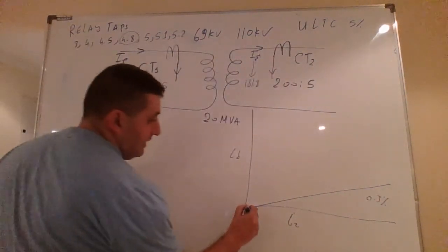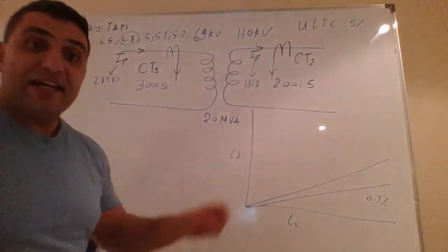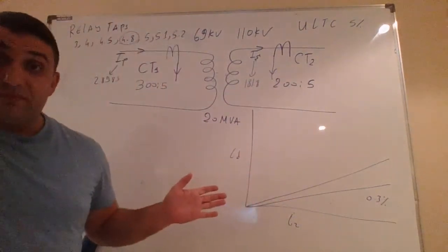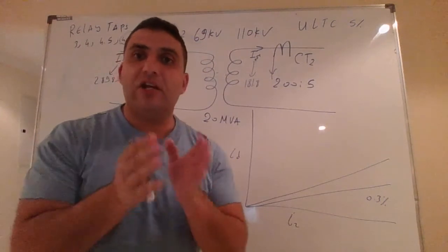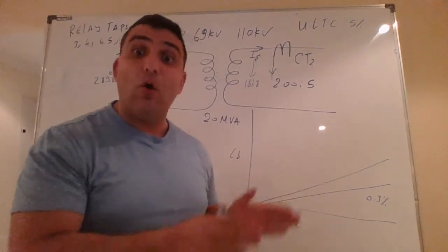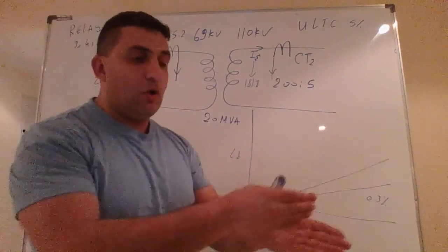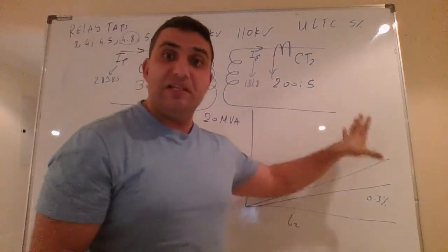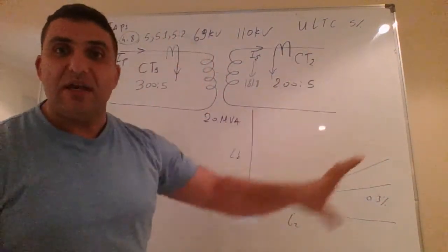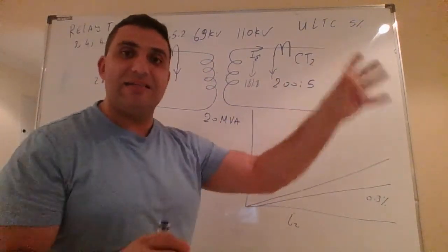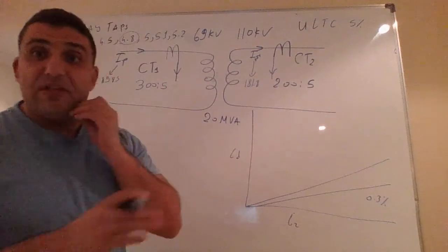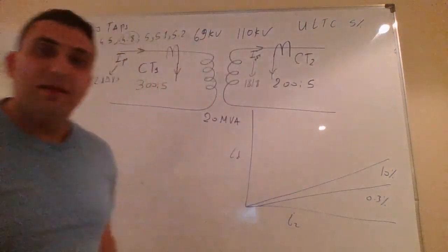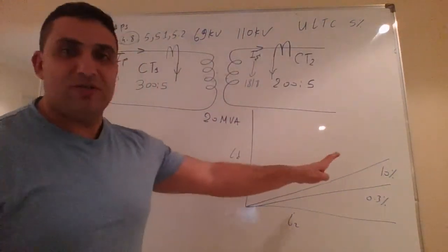The second error that we discussed was the CT error. Now, two options. Either we will have the input data to calculate the CT error as we've done in the previous chapters, or we will go into the data sheet as we did in a previous homework. We go to a data sheet and we find a CT with a nominated error, and we say this is the CT type that we're using, this brand, and this is the error. For the sake of this example, I just want to say it is 10%.